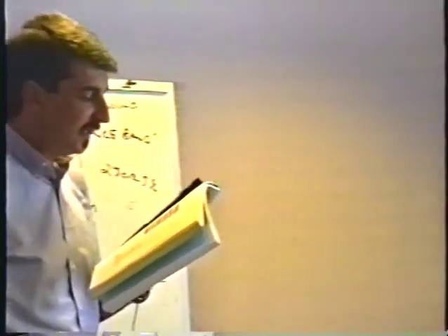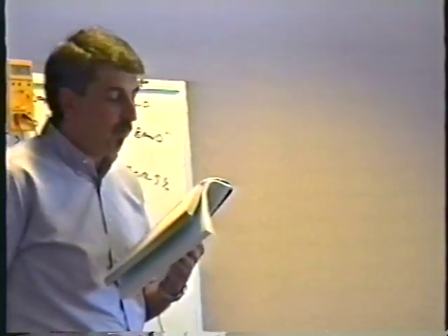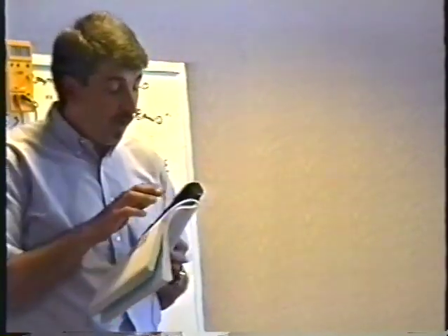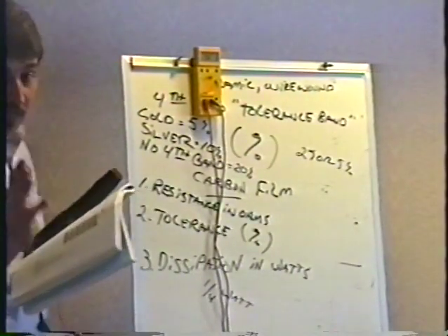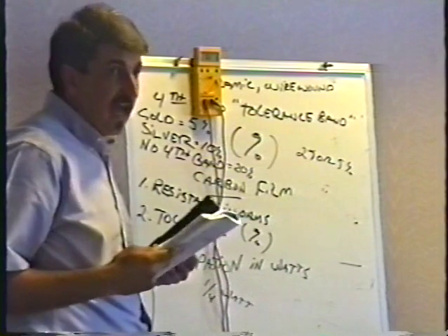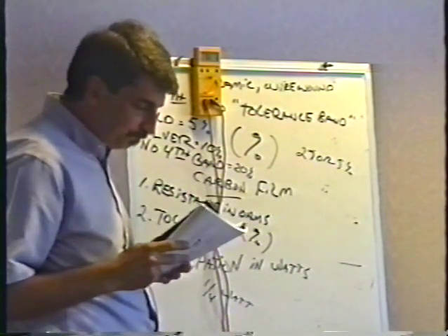Next one, God help you if you got number 6 wrong. Brown, black, black, we talked about this one. That's our tricky 10 ohm resistor. Remember that guy? 10 ohms, 5%. Number 7, brown, red, green is 1,200,000 or 1.2 megohm, right? If you put 1200K, you are correct. It is 1200K. That isn't how you would order it, and that isn't how it would be on the schematic diagram. It would be 1.2 megohm.